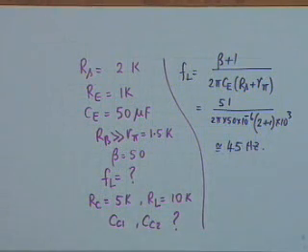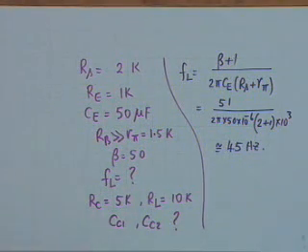45 Hertz. If you want 5 hertz, then you have to use what value of capacity? 450 microfarad, yes. Even 1000 microfarad is available. These are electrolytic capacitors. If it is a stereo amplifier and this is what is given to you, you say your design is bad, I will increase the capacitor 9 times, then I will get 5 hertz as the cutoff. And these things should be very obvious to you, where to change and what to change. Alright, FL is 45 hertz.